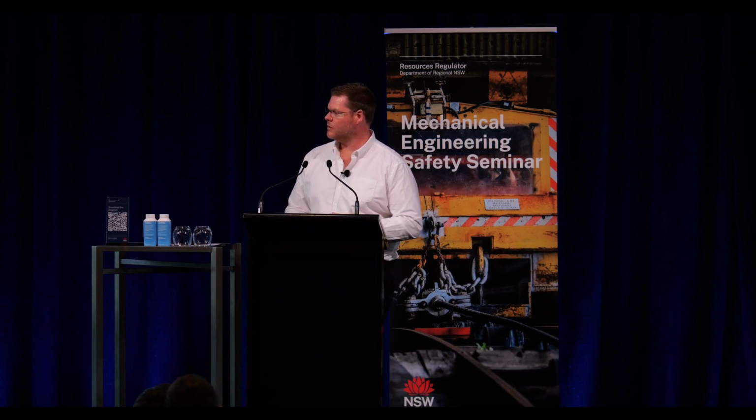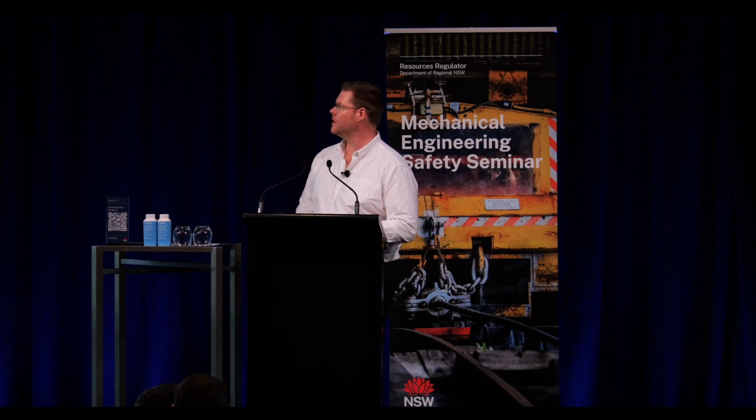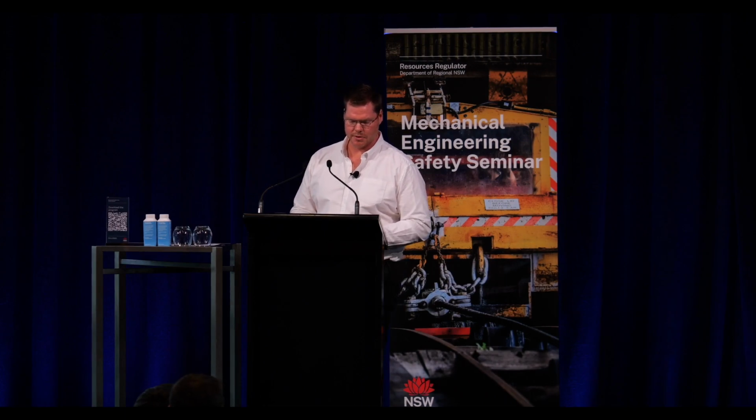So it depends on what type of equipment and what standard you're designing your equipment to, and what the equivalent limitations are for the fleet angle. But you also need to factor in your rope construction, because depending on your rope style, they also may have a higher or lower fleet angle tolerance.